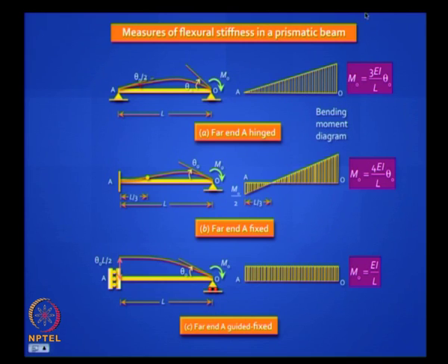See, it is the same M0. In this beam, here you are not allowing any translation, and you are allowing free rotation. Here you are not allowing translation or rotation. Here you are allowing translation, but you are arresting rotation. Is it clear? So there are different degrees of stiffness, but these 3 numbers you remember,